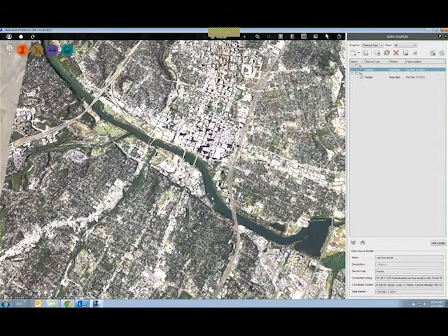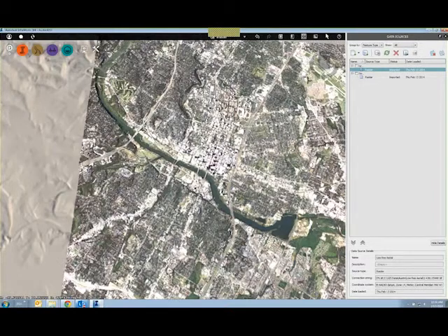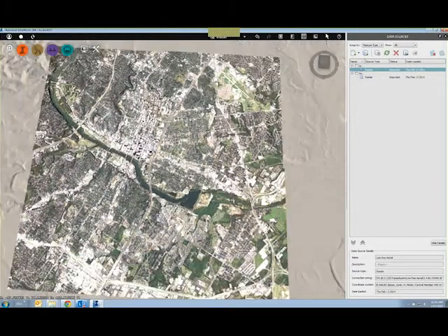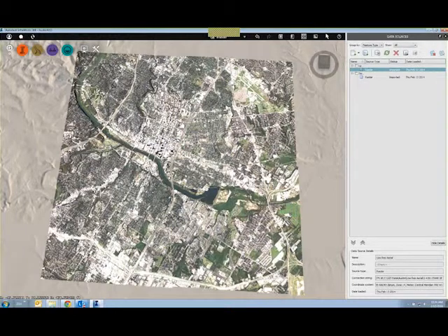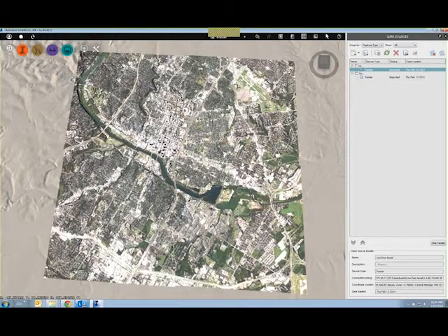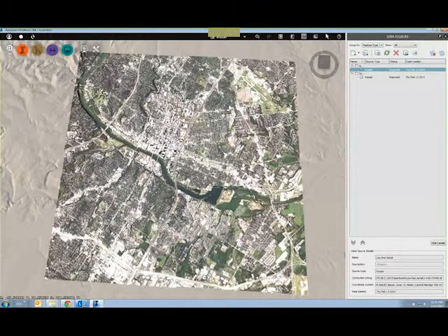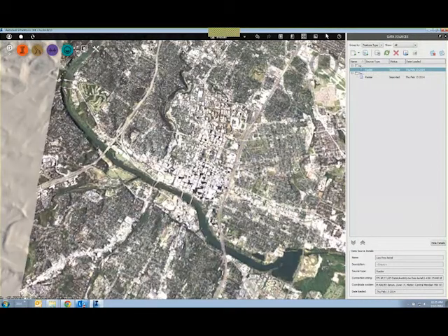Now, it's important to remember that GIS data is typically on a county or a city and sometimes even state scale, depending on where you are. So you'll want to limit data sometimes. With InfraWorks, if I bring in, for example, all of the buildings in Austin, there's approximately 400,000 of them. Since I'm really just interested in a little lot downtown Austin that I'm going to develop, I'm going to limit that data by setting up some of the options in my model.